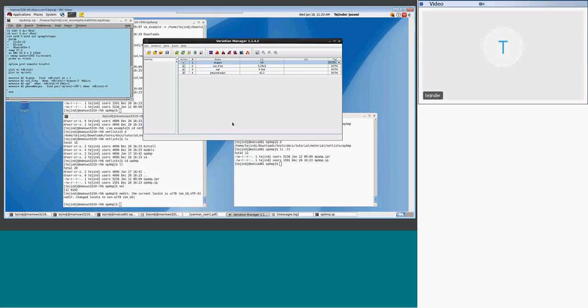If you don't enter any limits for one of your measurement parameters, it won't affect how the simulation proceeds, because Monte Carlo will give you the distribution with the mean and max anyway.